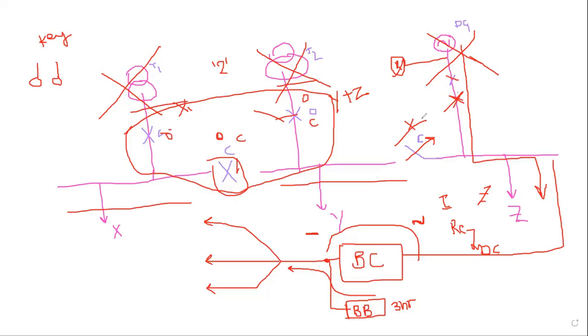So you can develop the scheme in that way also, but it is costlier. To make it simple, we are operating the DG set in manual, both the transformers working independently. If one of the transformers fails, the other transformer will take care of all the loads. If both transformers fail, the DG set will feed the emergency loads.